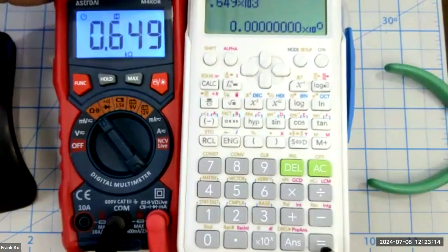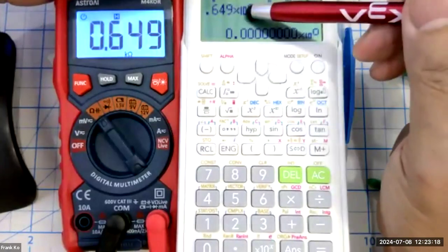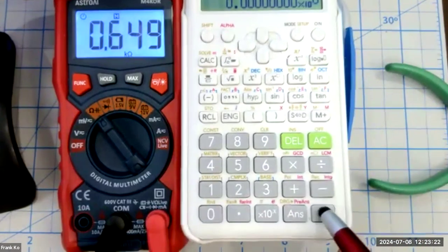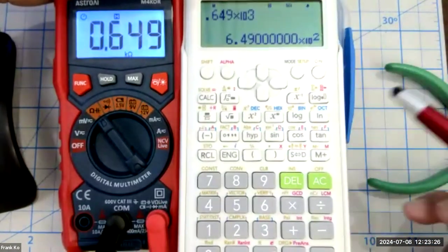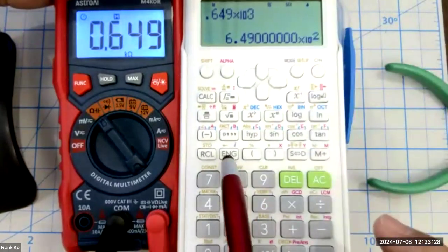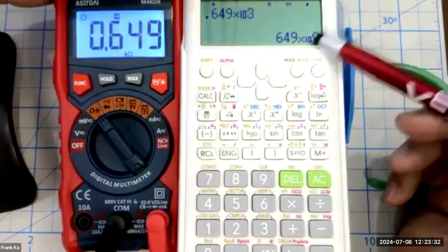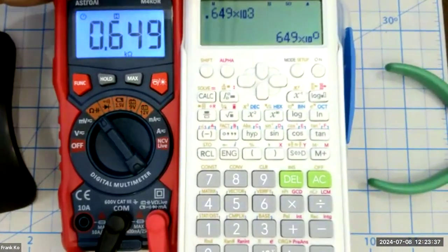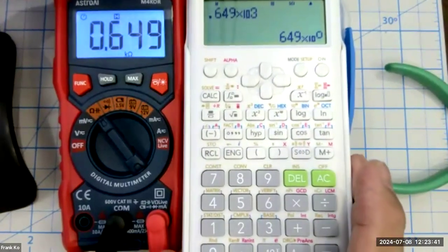This display is now keyed into the calculator. If I hit equals right now, again, 0.649, 10 exponent 3 is kilo. If I hit the equal key now, boom, I will get scientific notation, which is useless to me, but I have an engineering button, hit engineering. Lo and behold, 649, no power of 10, so that's a whole 649 ohms, which is pretty darn close to our calculated 650 ohms.